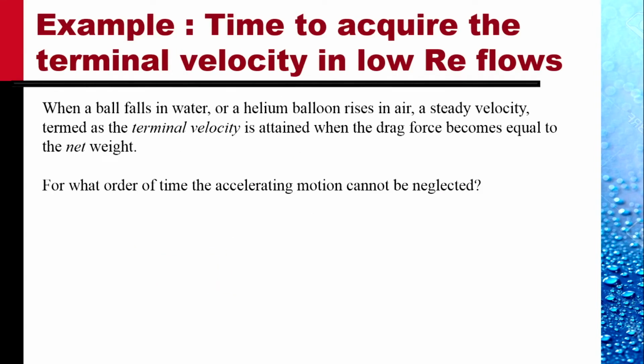Another example, let's calculate the time required to acquire the terminal velocity in a low Reynolds number flow. When a ball falls in water or a helium balloon rises in air, a steady velocity, termed as the terminal velocity, is attained when the drag force on the ball or the balloon becomes equal to the net weight.